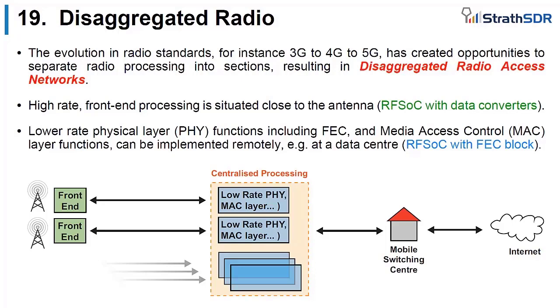So at the top of the radio tower, we have the radio head, and that's sometimes called the lo-fi, and the centralized processing at the bottom of a mast or in some central location. We might call that the hi-fi, the higher physical layer at the kind of high level. And once again, deciding how we split the processing is part of the software-defined radio design.